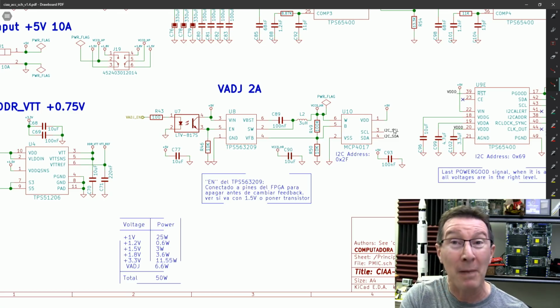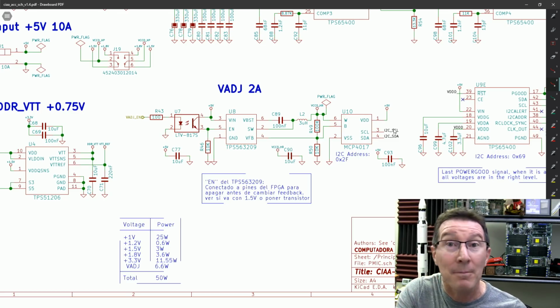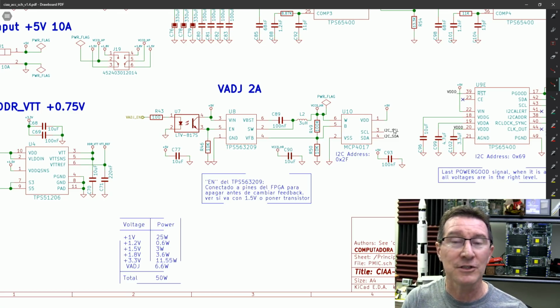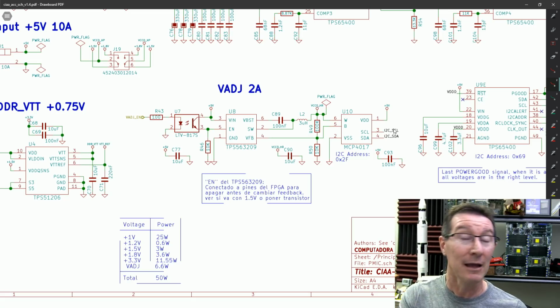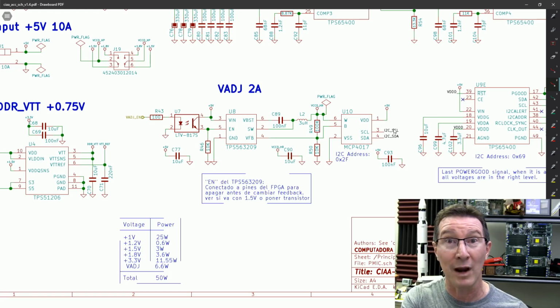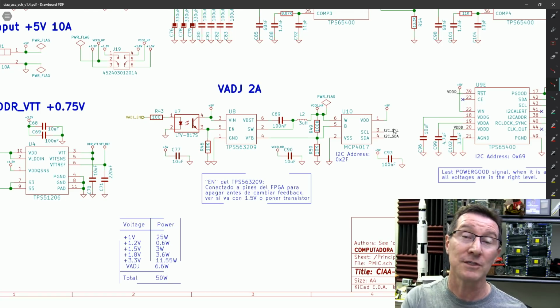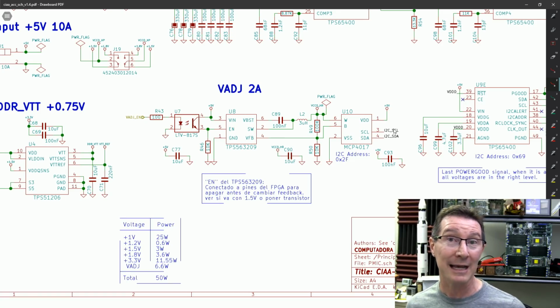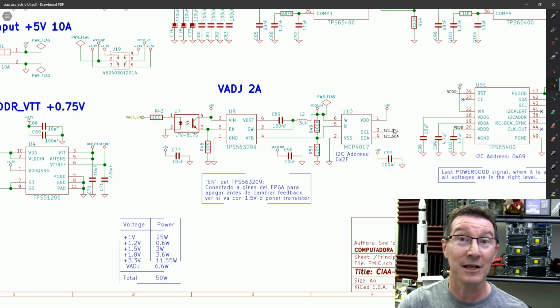Yeah, it might use a bit more power, and that might be a trade-off that you have to go through in your design. This is all part of engineering. Can I trade off the extra power for the 1.5K pull-up resistor, or even a 1K pull-up resistor, versus the calculated 1.8K pull-up that I thought I could get away with? It might be worth it because you save an extra reel.